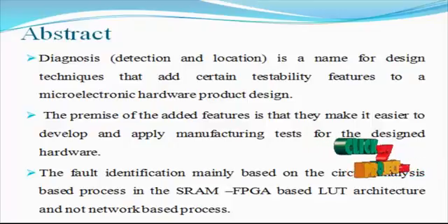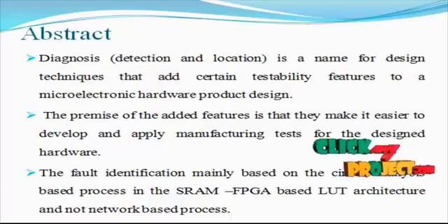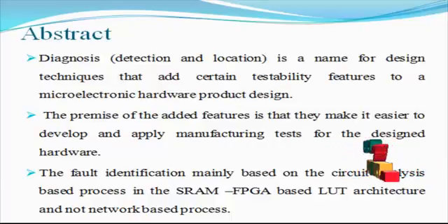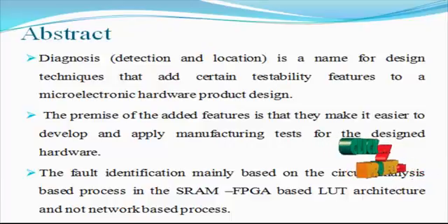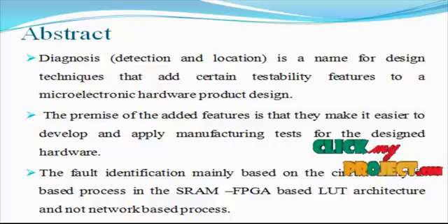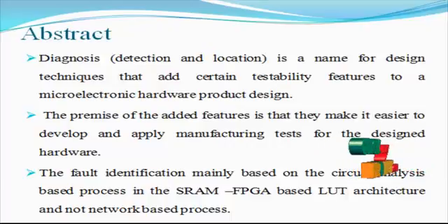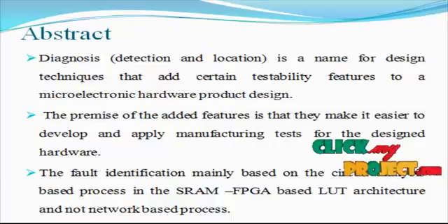Next we see the abstract for the project. Field programmable gate arrays have been widely utilized in digital system designs. FPGAs offer programmability at relatively low cost and good performance. An FPGA consists of logic and interconnect resources that permit configuring the uncommitted chip into the desired function for different applications. The common FPGA architecture consists of a two-dimensional array of configurable logic blocks, a programmable interconnect, and programmable inputs and outputs.